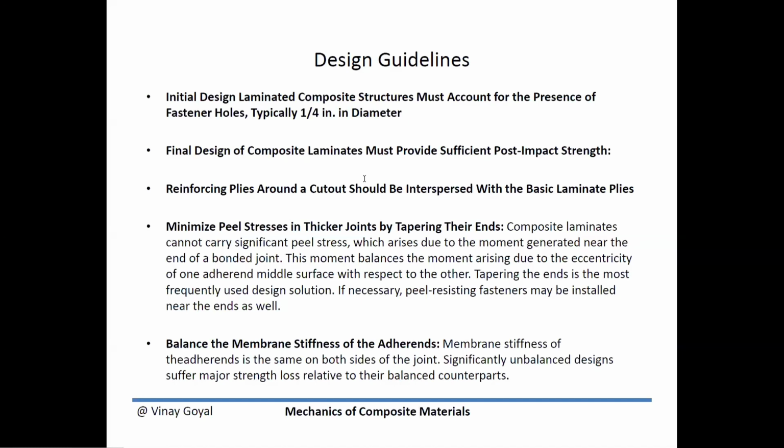Balance the membrane stiffness of the adherends, so make sure the membrane stiffness of the adherends is the same on both sides of the joint. The idea there is to reduce the imbalance so that you can increase the strength as a consequence.